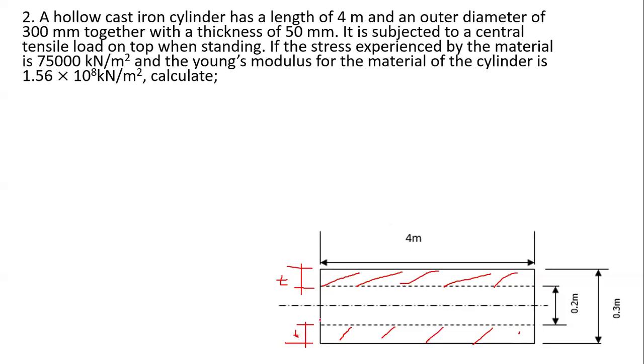Now, the internal diameter hasn't been given, which is our small d here. So if you're looking for this d, we're basically saying that small letter d is supposed to be equal to, if I call the outer diameter D1, D1 minus twice the thickness.